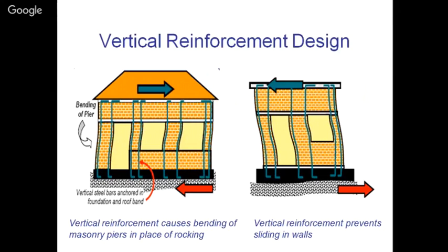This again is a topic which depends upon various things, various parameters, that what level of design you are doing. But you can definitely provide a vertical reinforcement to safeguard your buildings along with horizontal bands. So this is going to give you the more ductile behavior of the piers for the opposite direction motion, as we can see here.